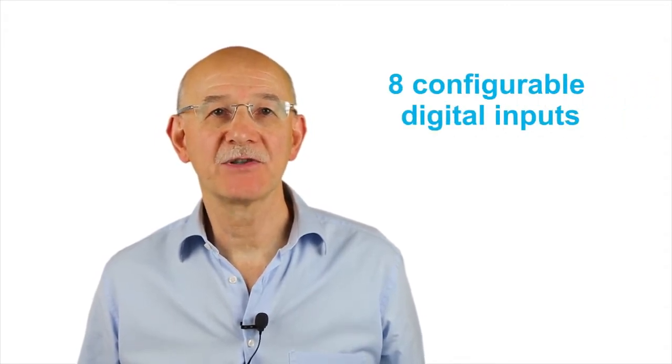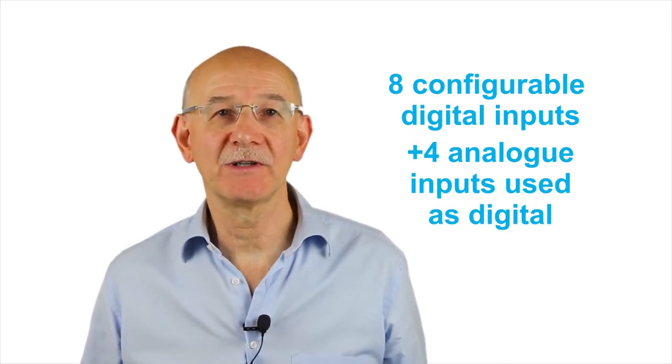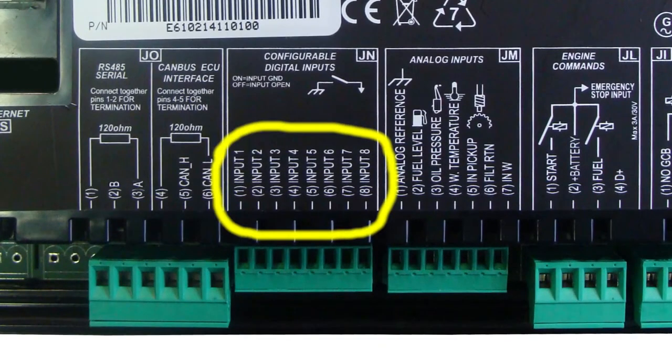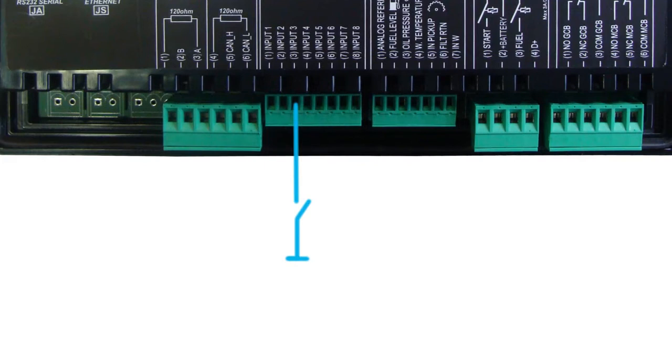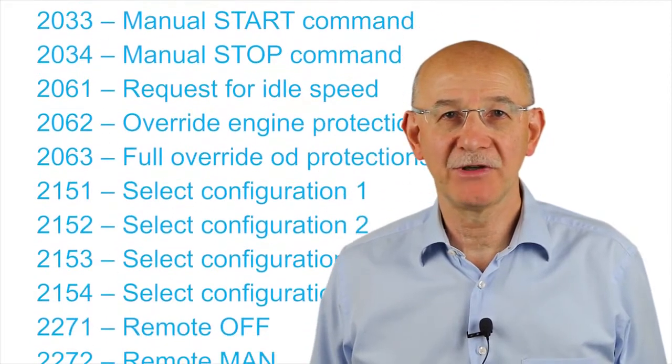GC315 has 8 configurable digital inputs. It is possible to add up to 4 more inputs, using analog inputs if not used for analog measurement. The 8 inputs are accessible by the A terminal of connector JN. By default, in order to activate an input, the input should be connected to ground, while it remains deactivated if disconnected. The 8 inputs have predefined functions. This can be easily checked by both G3 or through the controller display.